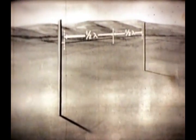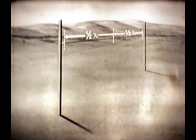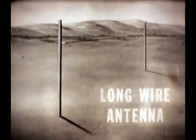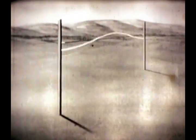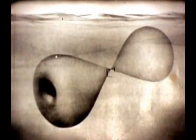Since the parasitic array is generally small and compact, it can be made to rotate, quickly pointed in any direction. Its useful distances, however, are limited. But when such wave patterns are to extend over transoceanic distances, then a different type of antenna is usually employed. This type consists of two or more half-wave elements which are connected end to end. It is called a long wire antenna. The elements are energized out of phase. Such out-of-phase energizing produces a pattern of about this shape.